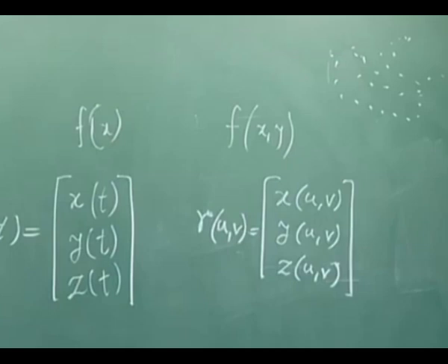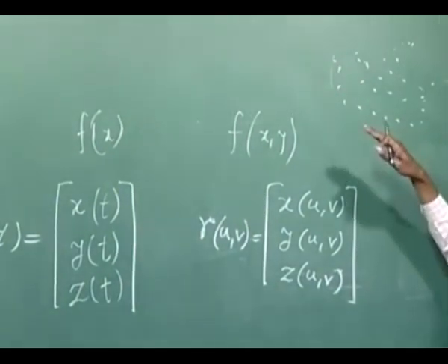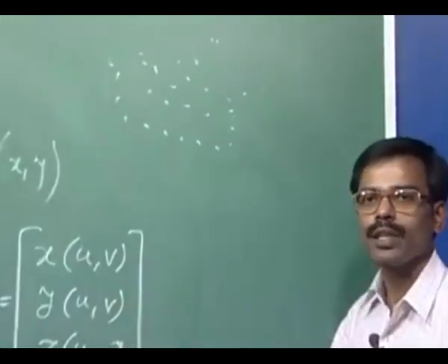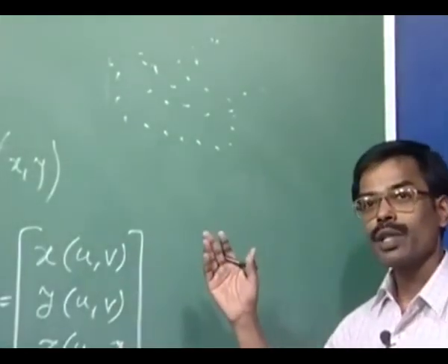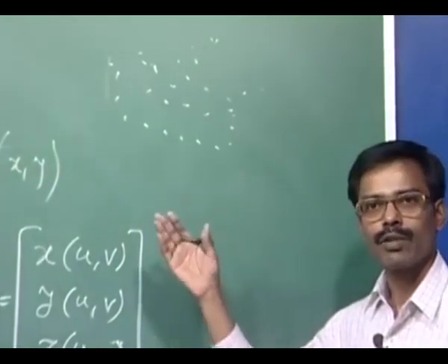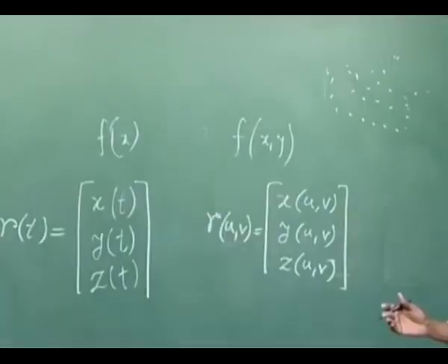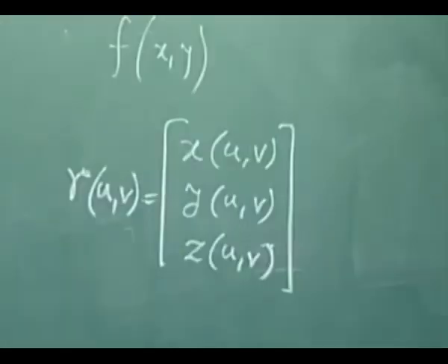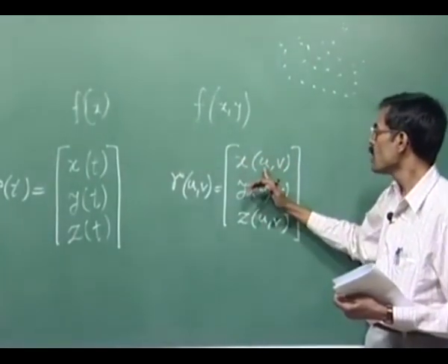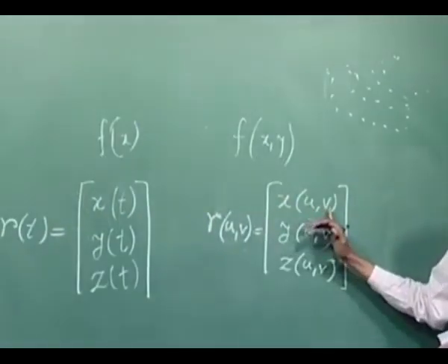You can say that suppose I have a bicubic expression of u and v, not just one expression but three expressions, one for the x coordinate, one for the y coordinate, one for the z coordinate. So, you can say that we have a bicubic vector function R with components x, y, z, that means three scalar functions, each of them bicubic with two variables u and v.